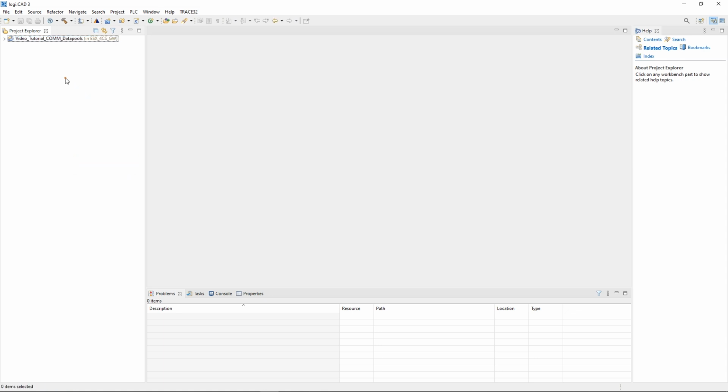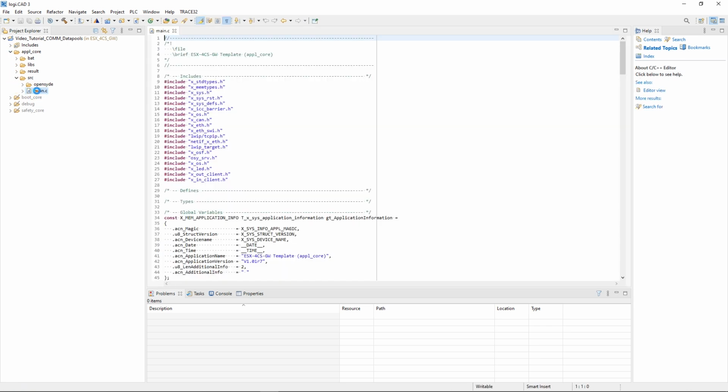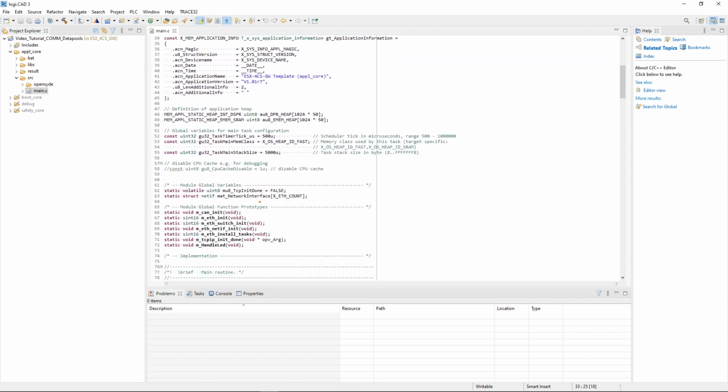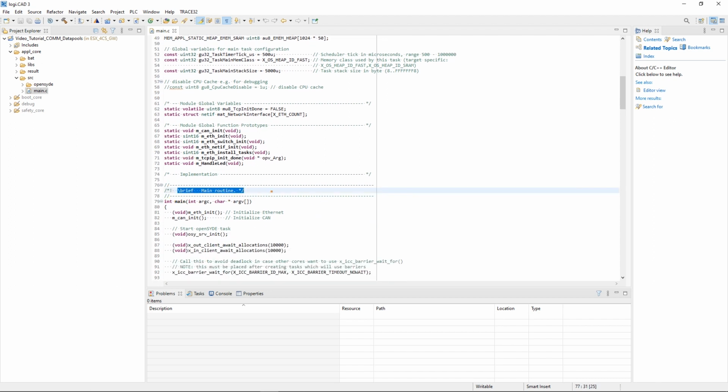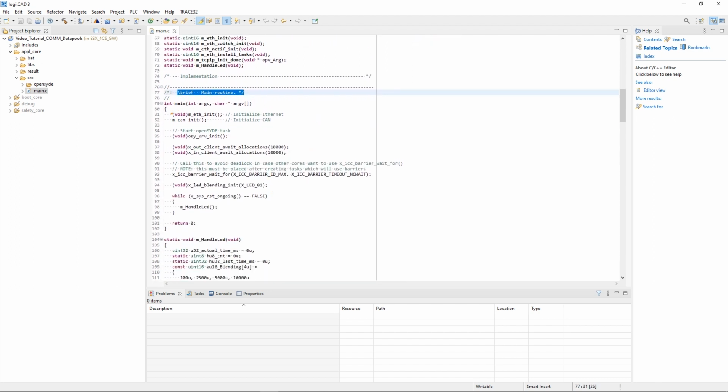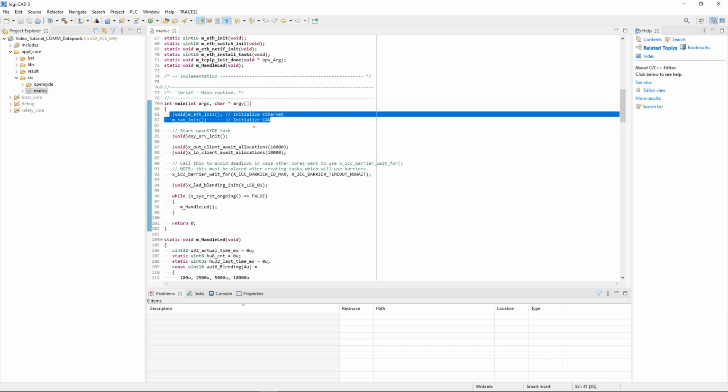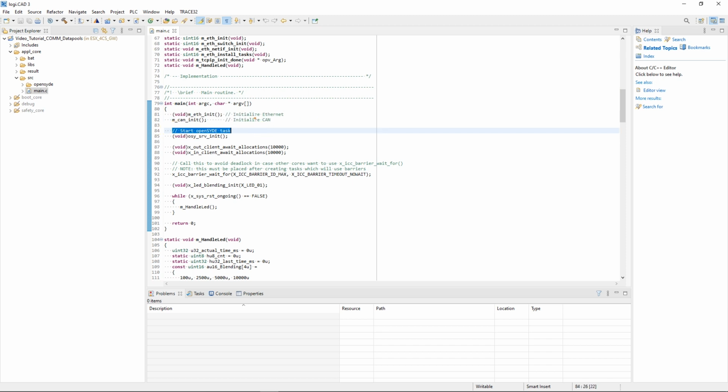So the starting point of the project is the program main.c. It starts with includes from the BIOS, followed by variable definitions until the main routine begins. This contains the initialization of the communication interfaces. The openSYDE server is then started, which enables us, among other things, to conveniently flash and use the data pools in connection with the dashboards in openSYDE. Finally, at the end there is a routine to constantly change the colors of the user LED.